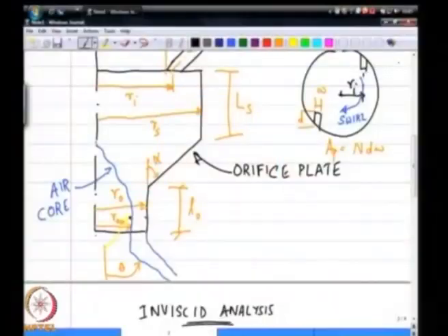because I can apply Bernoulli's equation on 2 points on a given streamline, and if all the streamlines are originating from the same stagnation pressure delta P, I can essentially apply Bernoulli's equation even across 2 streamlines at 2 different points, because they are all amounting to the same stagnation pressure. We will take advantage of this later on.